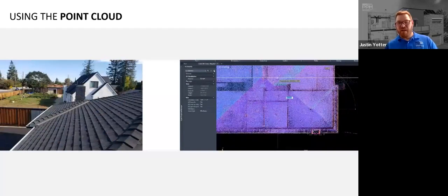If it was safe enough to get up on the roof with the scanner, you're in luck, and you'll have some excellent data to work with in drafting or modeling. It's always good to have photos open while you do this, regardless, to ensure it's correct. Scan data from inside an attic can also be very useful in displaying the behavior of the roof, either if you need to do work up there or if the roof is not accessible.